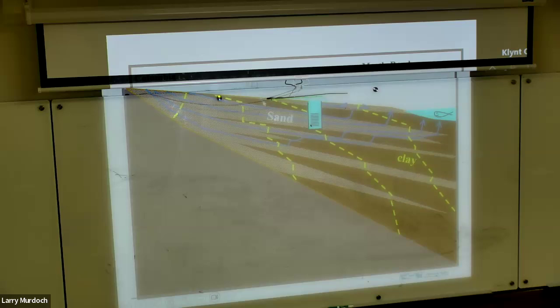But the effect is the same, and the cause is the same. You have to have a hydraulic head that is above the ground level. So if you can think about it, if you have an upward vertical gradient to a stream, then if you got an upward vertical gradient of 1%, and you drill down 100 feet, then the head at 100 feet depth would be 1 foot higher than the stream. So that well would flow.